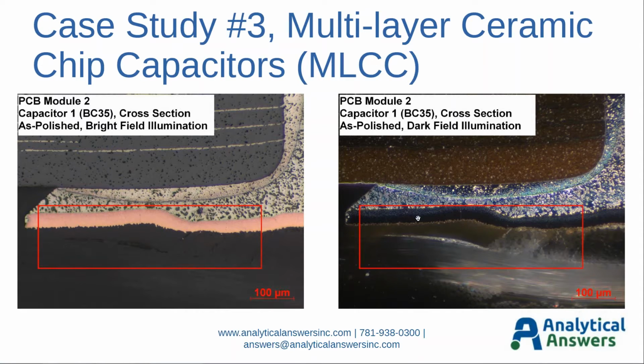Again, here's a dark field illuminated view of this particular delamination between the glass fiber filled region and the resin rich region here, and potentially a crack right here. And again, this caused buckling of the pad, the land that was associated with that MLCC.